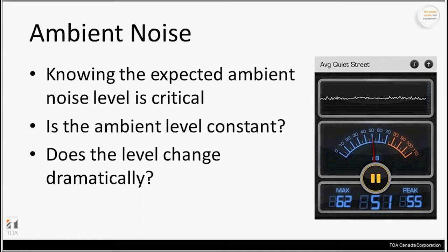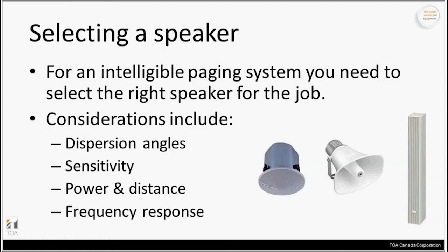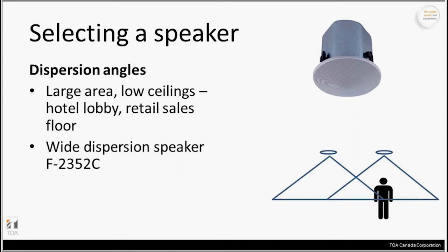This information that we just looked at is going to help us determine the type of speaker that we should use. So if we go to the next slide, selecting a speaker. For an intelligible system, you need the right speaker. So we're going to consider a few things: dispersion, sensitivity of the speaker, power and distance, as well as frequency response. These are all important things to look at. When we look at dispersion,